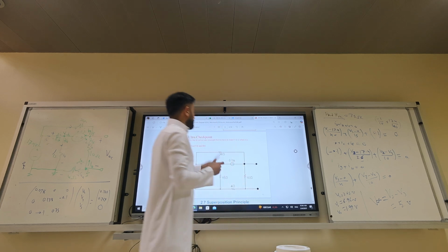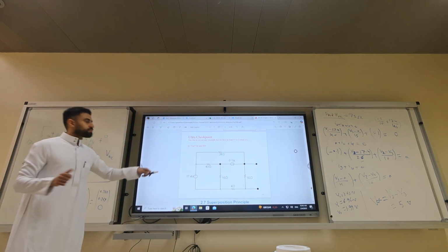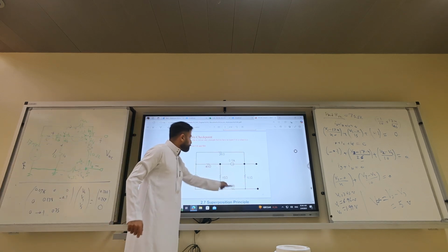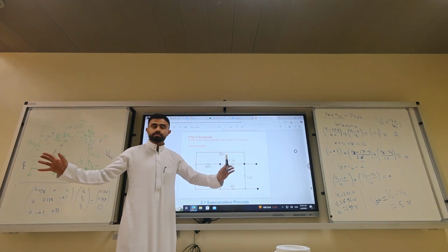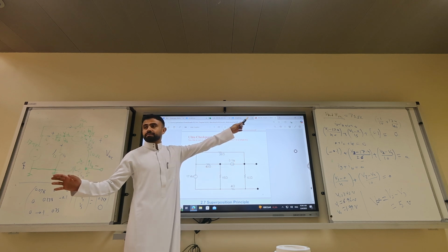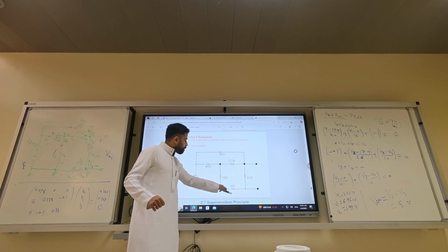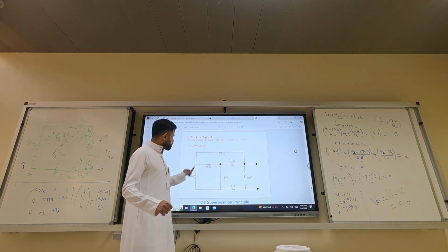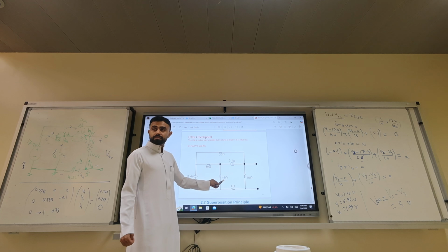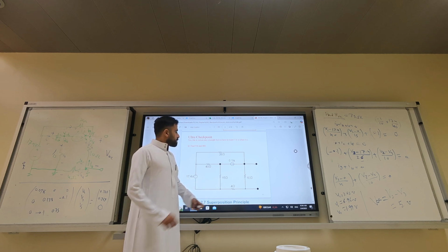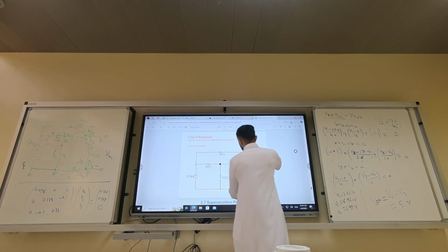again, let me explain this one more time. For our Thevenin, we said it's 10 parallel with 4 plus 26, which was 7.5. 10 parallel with 4 plus 26, because short circuit will cancel 14 and 15. How is it parallel?